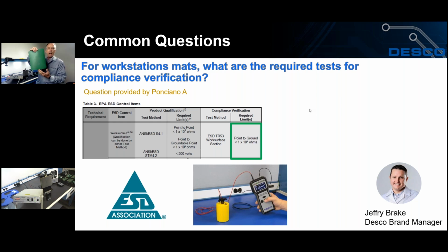So here's another, this just happens to be green. Here's the same 2-layer rubber mat material. You'll notice the color side, that's the dissipative side. And on the bottom, that's the conductive side. So this is the ground plane that Jeffrey's talking about. When the charge goes on the surface, it goes through the surface, and then it speeds off to ground. So the intimate surface is what we want to be dissipative. Great, thanks, Greg.